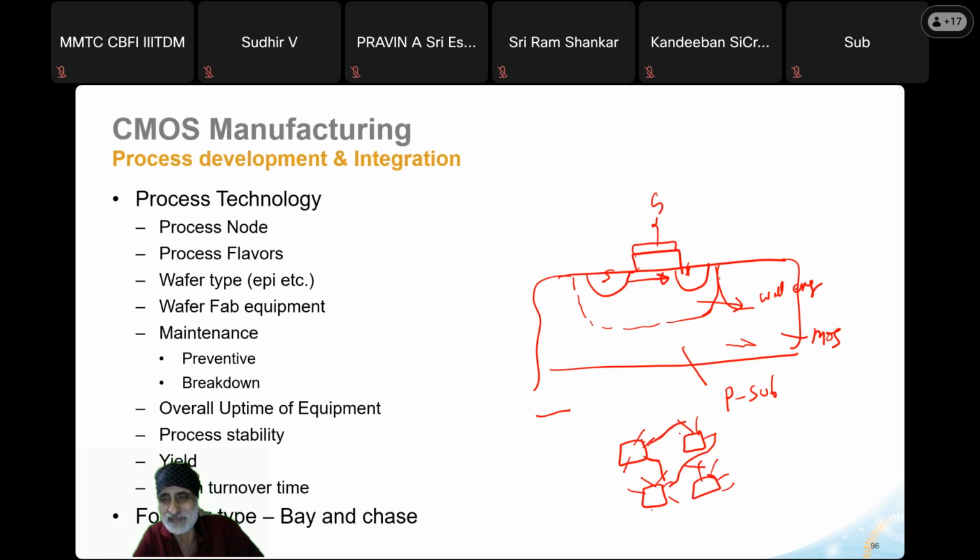They also take silicon. So if I want to make a very compact, very high component density, I want to make the components very close to each other, then I won't get enough space for making these contacts. So what I can do is go for more metal layers. I can go for more layers on top of it, like we have multi-storied flats. The concept is the same. Area is limited, so you build high-rise buildings. The same way here, because our interest is to have more components.